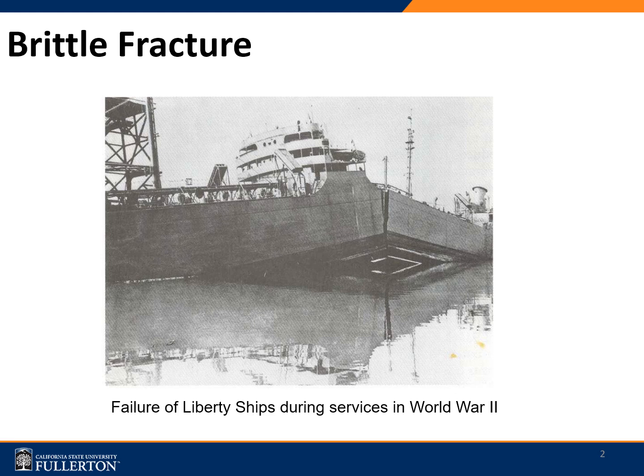And then they soon came to a conclusion that the sub-zero, extremely low temperatures in the deep sea could have facilitated the brittle fracture. So they could find a relationship between the brittle fracture and the temperature at which the material was exposed.